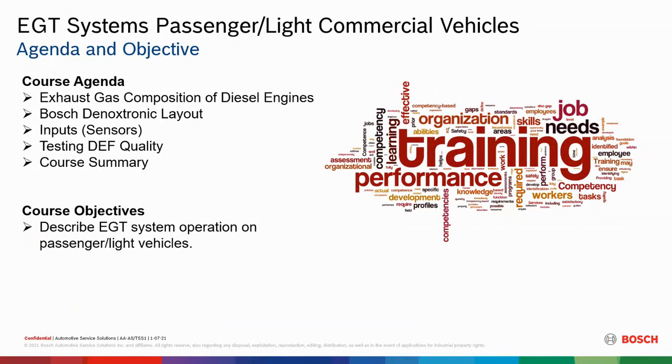Okay, so our course agenda is we're going to go over exhaust gas composition of diesel engines. And really, this is pretty much the most important part of it, honestly. I know we're going to talk about the after treatment system, but the reason why this is most important is the after treatment system suffers due to engine performance problems. And a lot of things go unseen and repeat failures happen in the field. We're going to talk about why it's so important to have a good running engine and verify that prior to the repair of a fault of an after treatment system.